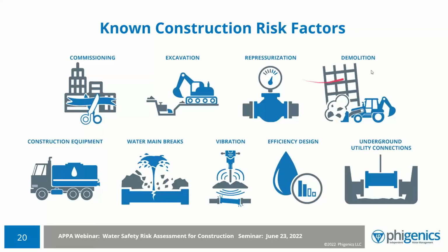In demolition, it could be below ground in terms of utility tunnels and things, but a lot of people don't think of above ground. There are many studies that show that above ground demolition of taking down buildings, road construction, or civil pathways creates plumes of dust that go up into the air and settle into an adjacent or nearby cooling tower and foul it. And the cooling tower is receiving a dosing of treatment for standard operations, not for a giant influx of soil and sediment into it that then begins to grow Legionella, and then drift occurs and it goes out and becomes a community outbreak.